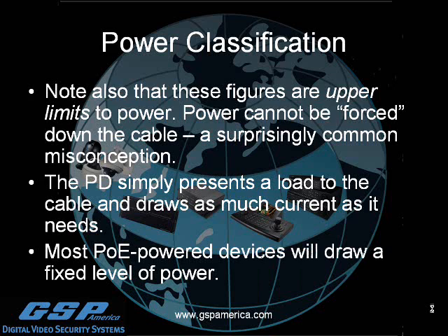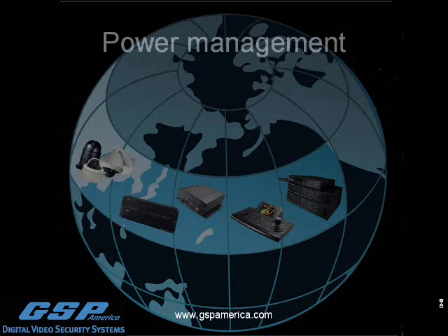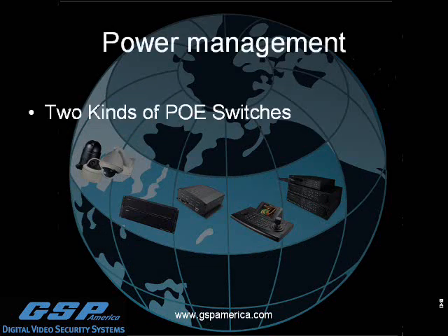Most POE powered devices will draw a fixed level of power. So again, a POE switch does not push power down the cable. The device actually pulls and draws the power that it needs from the switch. We'll go into more safety features as we go here.